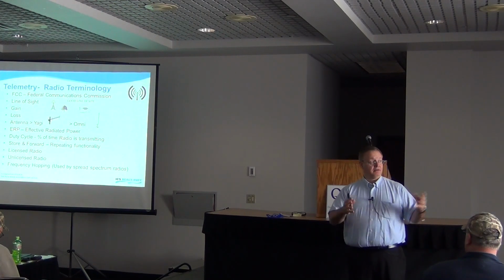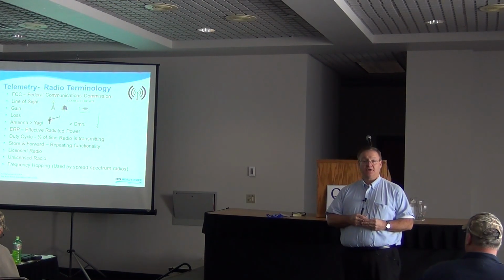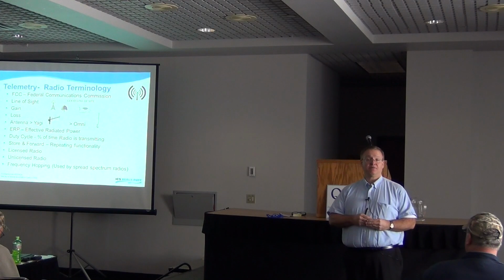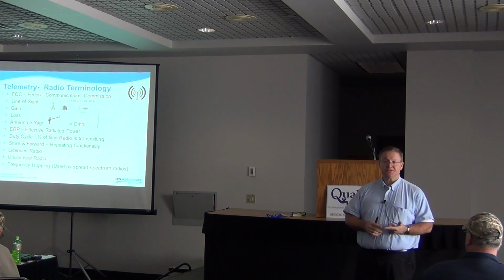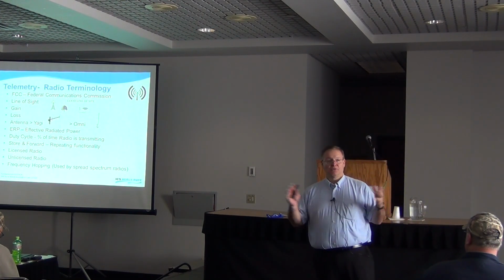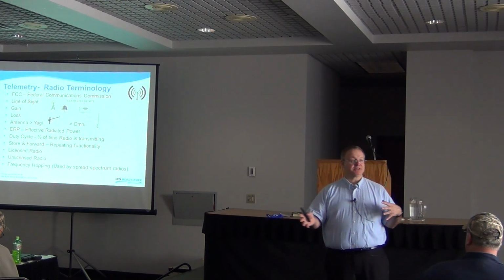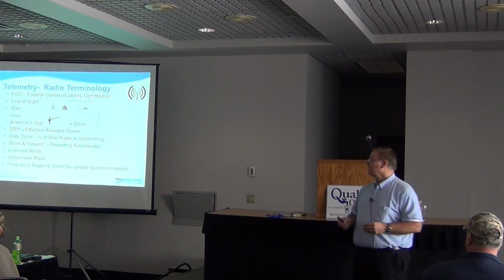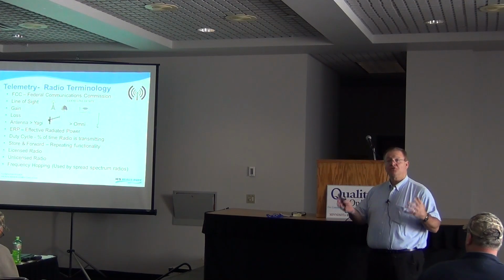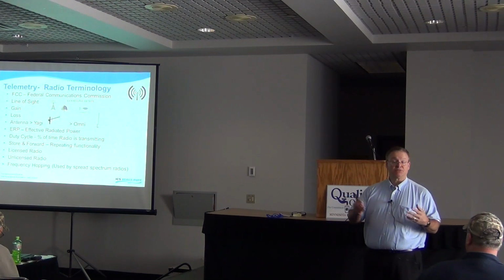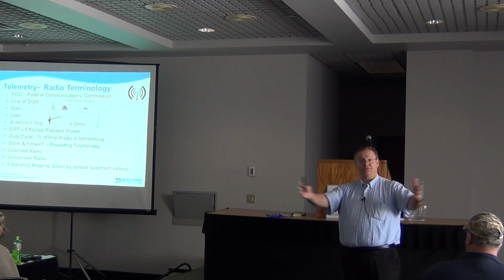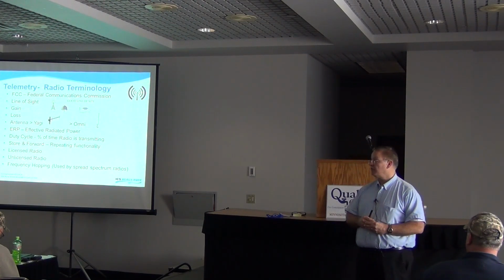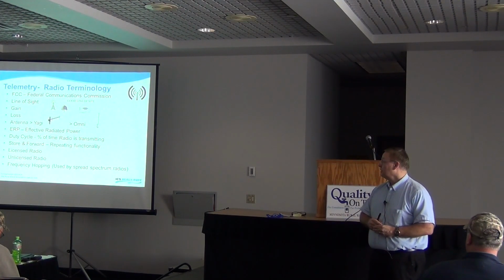In metropolitan areas, you can get a lot of use of these frequencies because everybody can use them. Your home security systems, your baby monitors, most of your computer networks that are wireless at home will use those frequencies. So you get a lot of people using them. And they don't always make for the most reliable system for water and wastewater because of the geography that you have out there and how spread out things are.